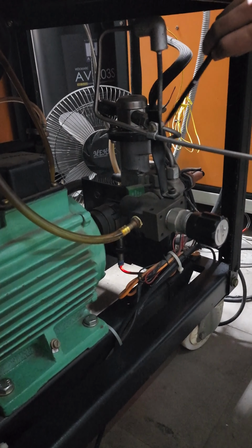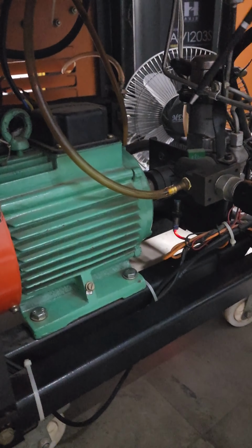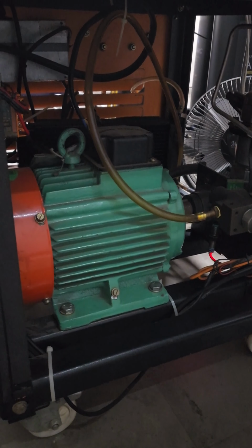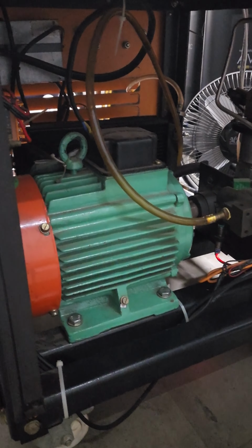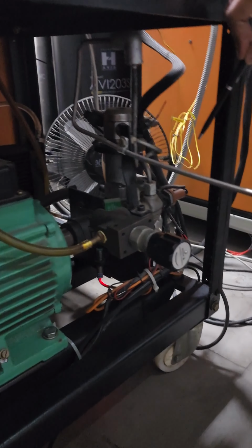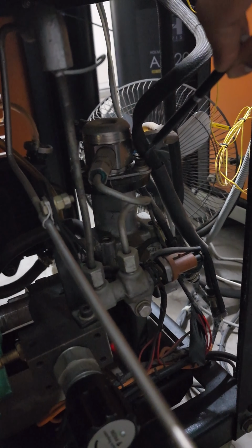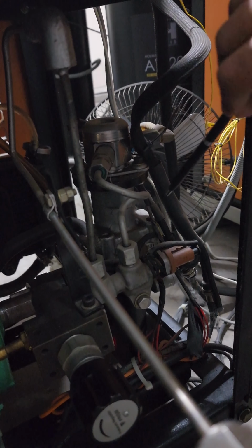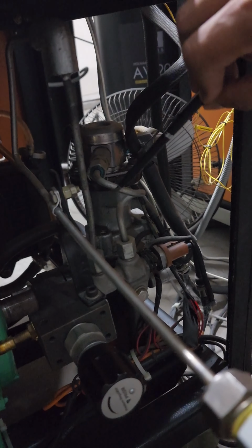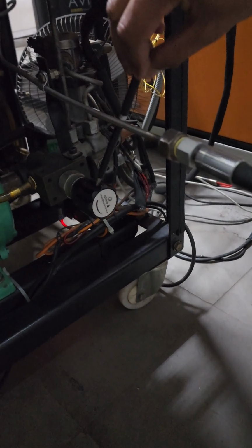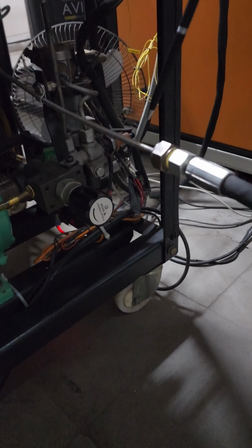The GDI pump is run with the help of this 5 horsepower motor. This motor runs the shaft, which actuates the cam and follower. This cam and follower is connected to the GDI pump, which pushes the spring and the plunger that generates the pressure. The fuel is pressurized within the common rail, which is then controlled through this valve. So we can increase or decrease the pressure in this fuel line according to our requirement.